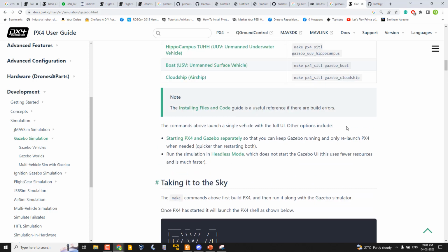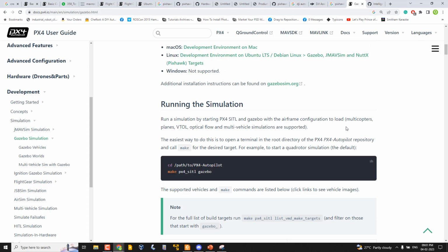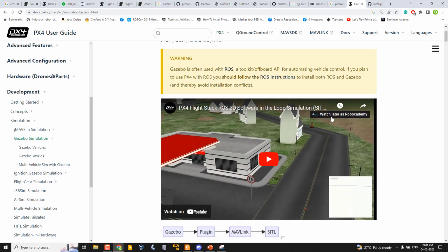The problem is that when you add a new robot in Gazebo, for example in the case of a mobile robot, we have a command velocity, right? Similar to that, a drone has a command velocity. So if you have multiple drones, you should have namespaces like drone1 command velocity, drone2 command velocity.